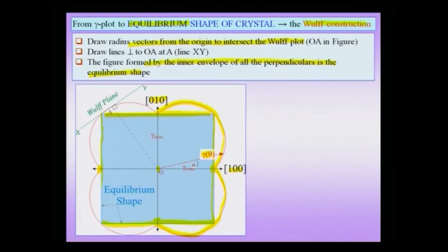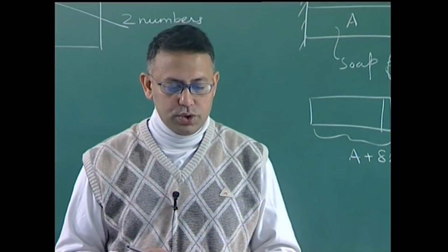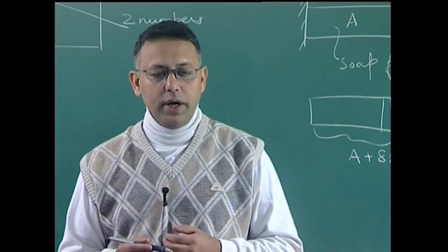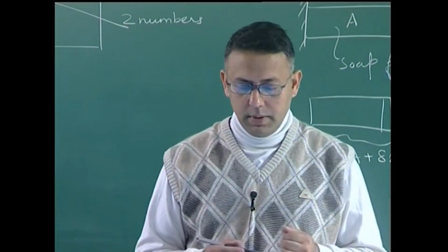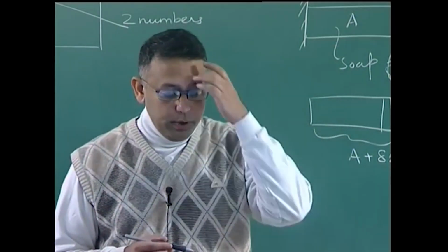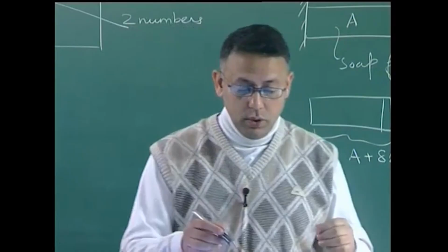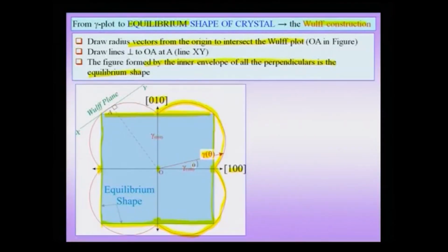Of course, this is a schematic here and various crystals would have different kinds of equilibrium shapes, which may have 111 surfaces, 100 surfaces, but typically these are low index surfaces which are thrown out by a crystal. A point to be noted is that those low energy orientations, the cusp orientations, are the more preferred ones, and typically will show up in the Wulff construction.